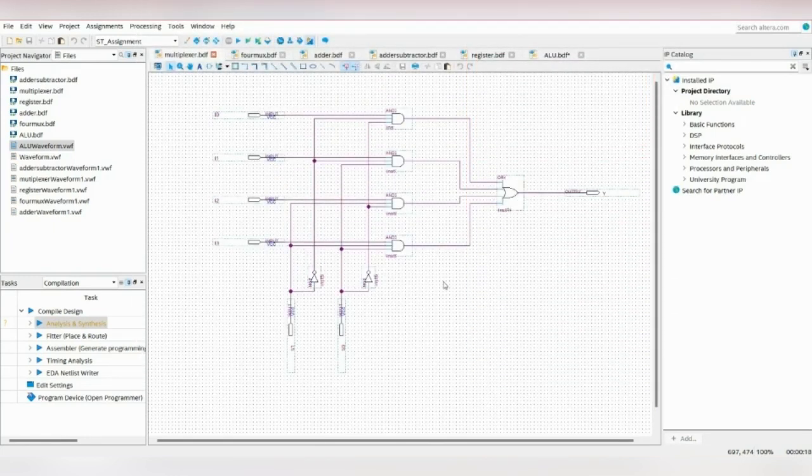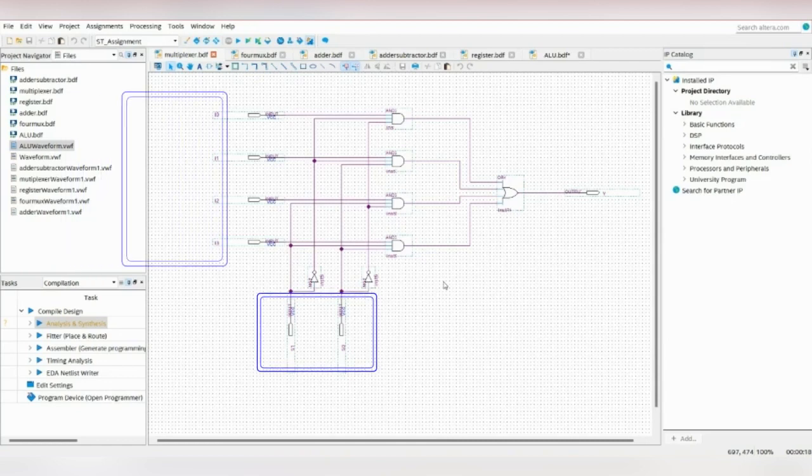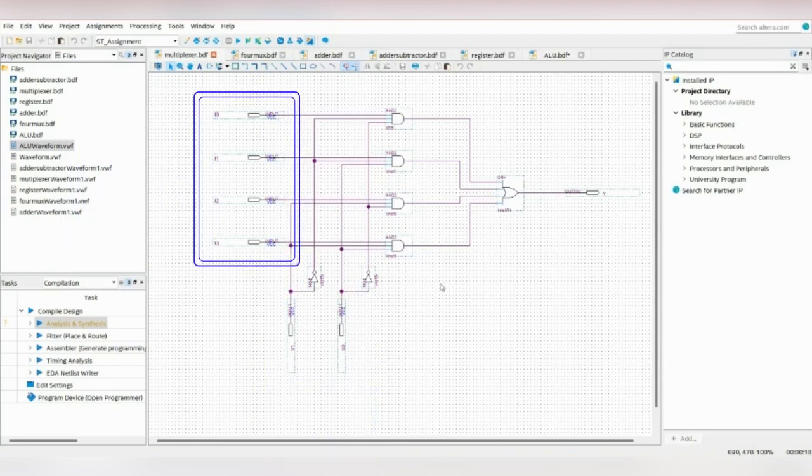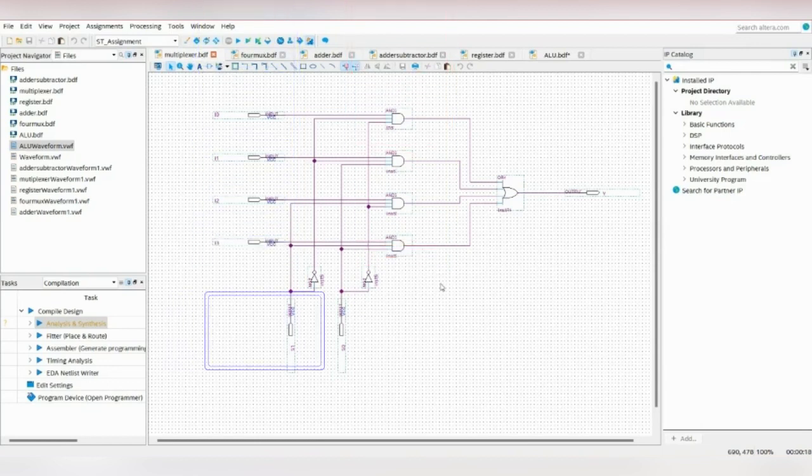A 1-bit 4-1 multiplexer has two control signals and 4 inputs. The 4 inputs I0, I1, I2, I3 will connect to AND gates respectively. For the control signal, S0 will connect to the second and fourth AND gates, and not S0 will connect to the first and third AND gates. S1 will connect to the opposite of the S0 connection. Finally, all the outputs from the 4 AND gates will connect to an OR gate.